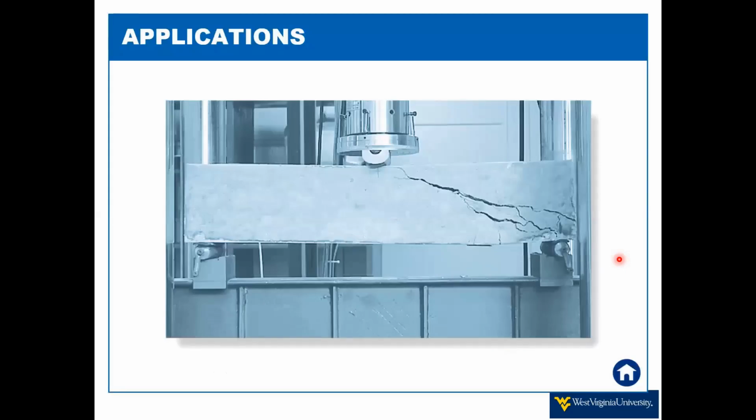If that doesn't make any sense, this picture shows a little better of what I mean. So we have this concrete block here being bent between 3 different points, one here, and then here. We call that 3-point bending, very original name. And concrete's well known for not being very good under tension. So what you end up having here is some tensile stresses developing in certain parts of this beam and at certain angles. And by doing some stress transformations that we're going to do in this class, you can find where that's going to occur in your material.